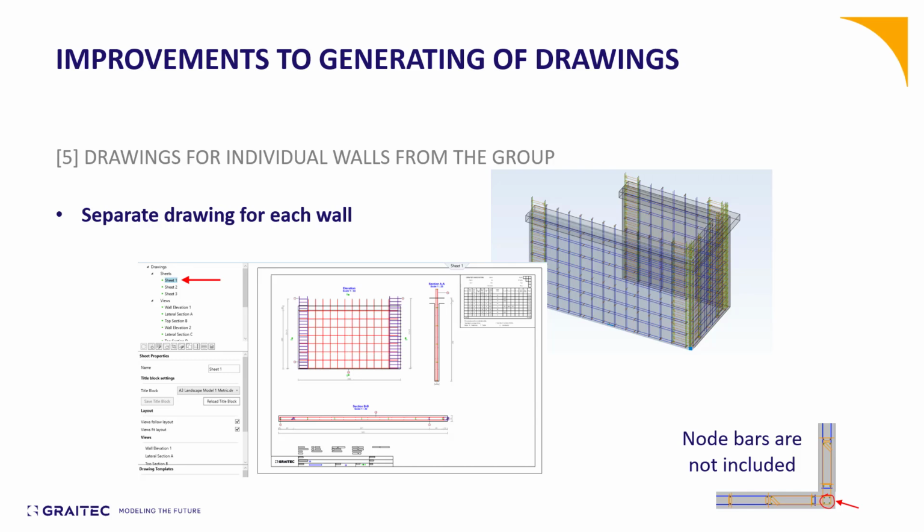But note there is a limitation in this release. Nose bars, like the four vertical bars on the right down picture, are not included in such drawings, so we should add such bars manually when we edit such drawings in CAD software.